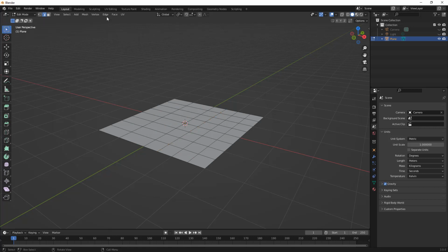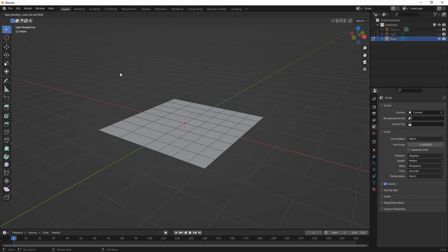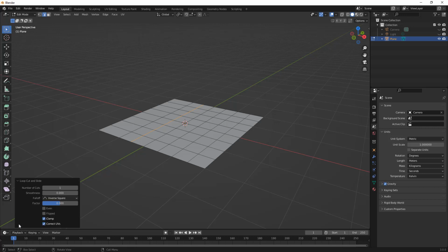So when we're on the Loop Cut tool, it behaves like Loop Cut and you need to hold down the mouse button. However, when you're on the Selection tool and we come down to Loop Cut and Slide, it allows us to click the orientation and then slide without holding down the left mouse button. Then we right-click the mouse button to place it back. And once again, you'll notice a new menu appears. We have some options for things like fall off, and that'll become more important as soon as we're not working on a plane.